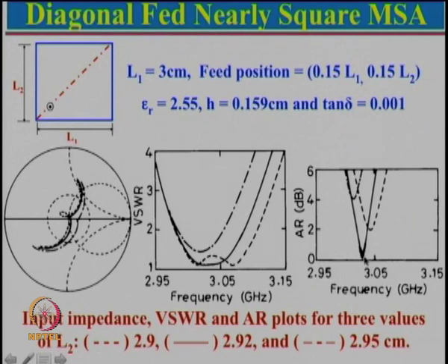So, we can see that the best axial ratio is obtained when there is a kink, and you can see that the axial ratio is relatively poor for the other 2 cases. So, for optimization of these configurations, I always advise look at the Smith chart plot, and if it is a kink, that is what will give you the best axial ratio.